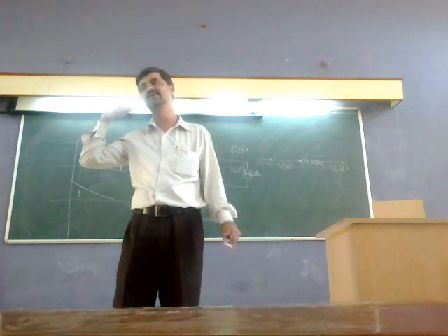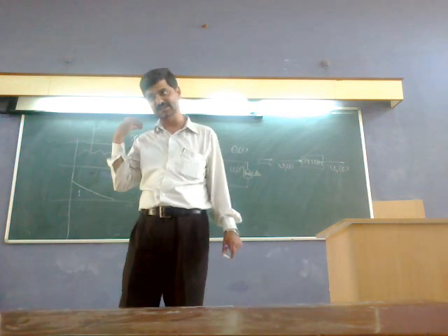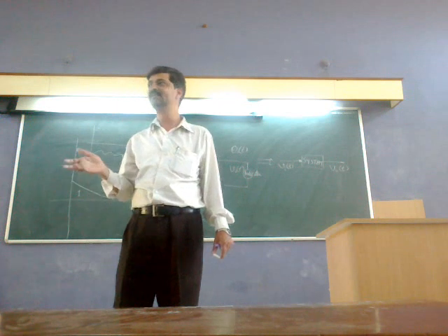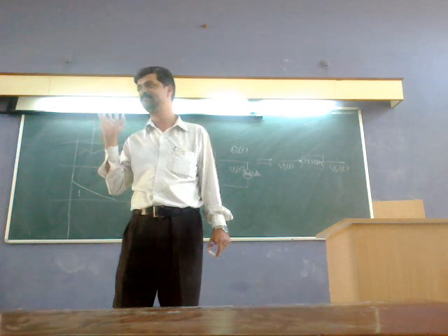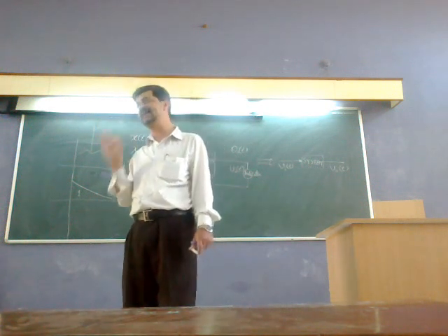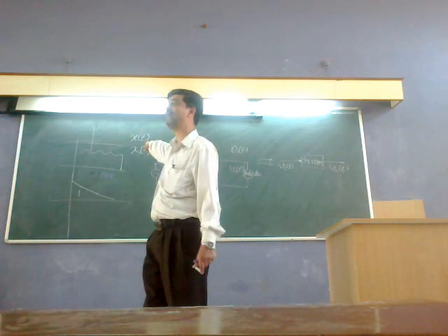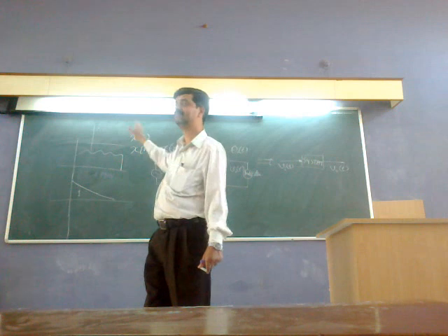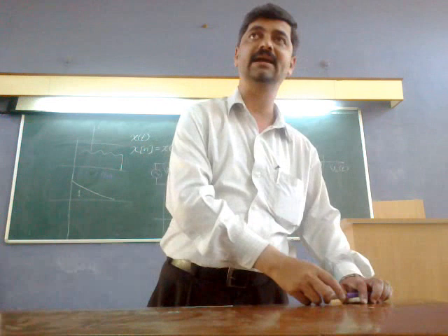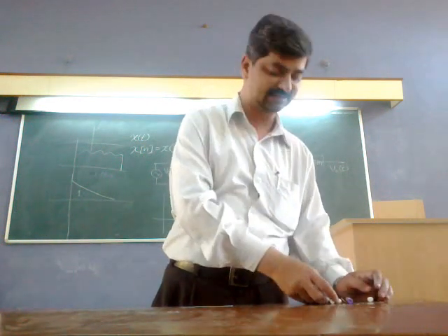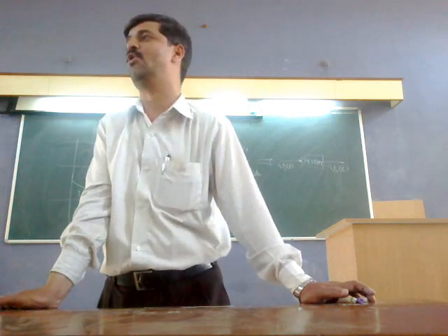So discrete to digital is obvious, and with good quality ADCs available, the difference between discrete and digital is hardly of any consequence. So we can say that the signal x(t) gets converted into the sequence x[n]. Is it clear? The signal x(t) gets converted into a sequence x[n], which is an array of numbers, and further I say can be stored in digital form.